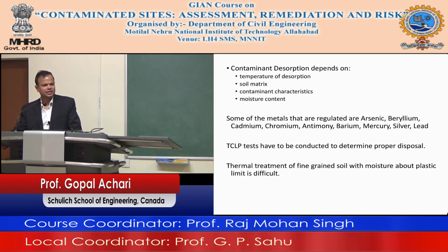Now think of what the gas would comprise of. It's not pure gas. It's very dry. You'll also carry some flue material, like solid particles. So you may have to go through a cyclone to separate the dust particles from the gas itself. Then it runs through an oxidizer where you oxidize the gases, you cool it using a quencher, eventually filter it, and then vent it out.